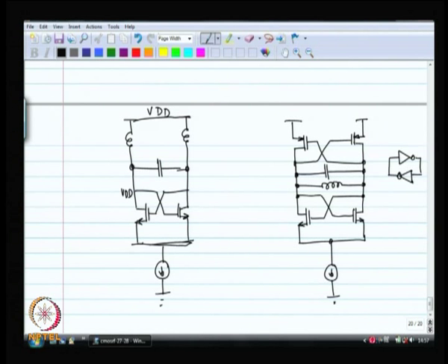right across. So, this also is quite popular, right, and in this case the negative resistance that you are getting is even better than before, because now you have the GM of the NMOS plus the GM of the PMOS, right. Of course, you also have the RDS of the NMOS and the RDS of the PMOS, but if that is not of concern compared to the resistance in the inductor, then this could be a potentially better topology. Anyway, so these kinds of topologies are used routinely.